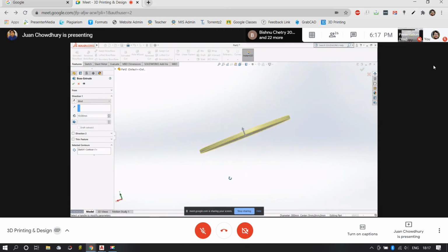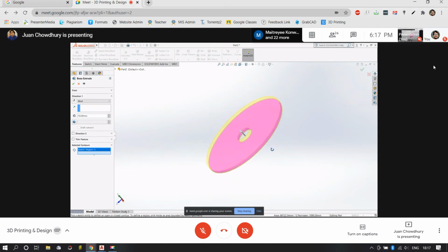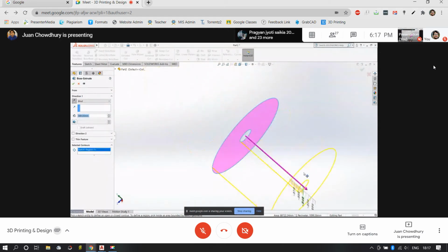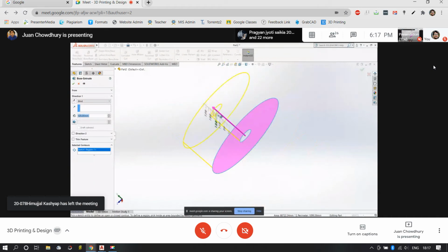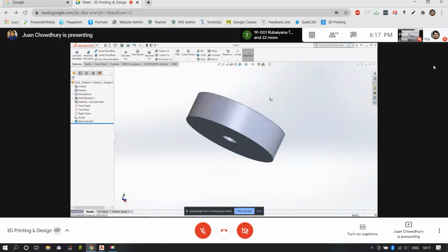The disk is without the hole. So here, if you see selected contours, you can select this contour and right click over there, and clear the selections, remove what is being extruded, and then simply select the profile. Now as I increase the height, it can be done with that arrow. You can type it in, or you can also pull. You can pull in both directions. So let's not keep it that way. It says 85. It feels fine at 85, looks particularly stable.